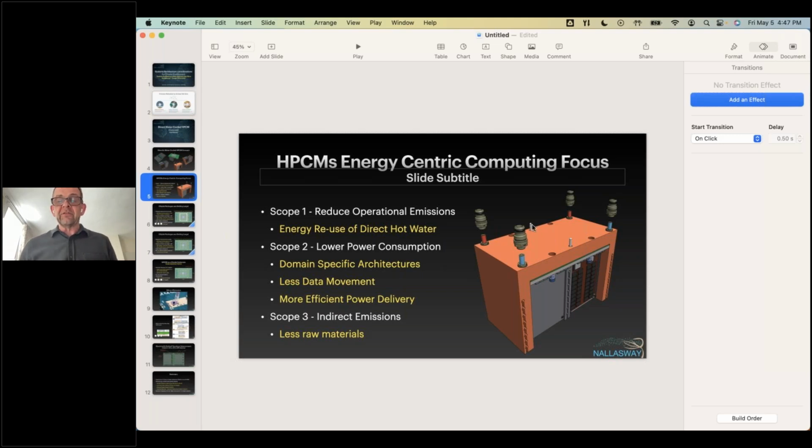And it's 48 volts. So it's a super, with big fat bus bars, or you'd have local power supplies stepping down from the data center voltage levels of 370 volts or whatever that is. I've been talking to OCP Regional Summit. I talked to Murata. They do the step down to 48 volt power supplies. So they're in our work group, just seeing how they could build that into the wall, and we could get efficient power delivery. So the 48 volts comes in extremely efficiently, and then you step down from there. Makes sense. Okay, thanks.